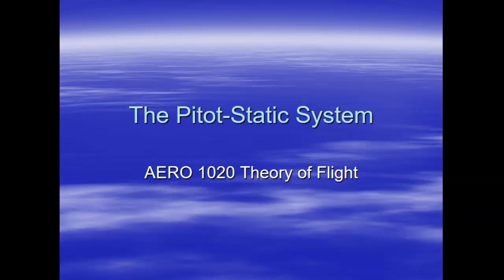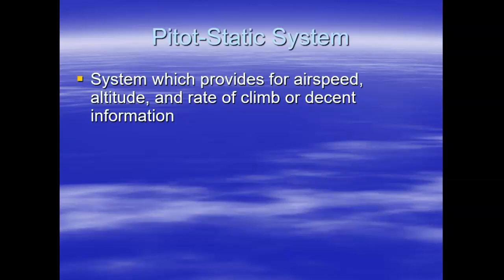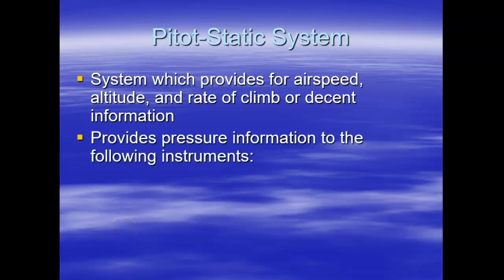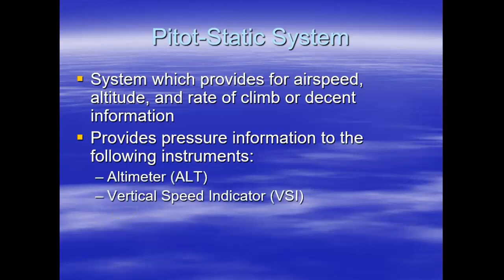Welcome to AERO 1020 Theory of Flight, presentation number 4 on the Pitot-Static System. The Pitot-Static System provides airspeed, altitude, rate of climb, or rate of descent information. It provides pressure information to the following instruments: the altimeter, the vertical speed indicator, and the airspeed indicator.